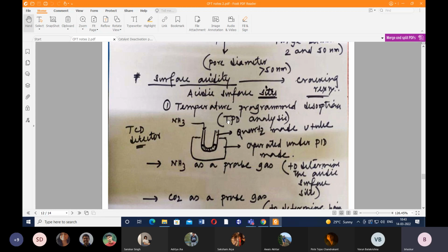This is treated as the active surface area or surface sites. In catalytic reactions, we talk about surface sites instead of surface area. By now you know what our active surface sites are and what our inactive surface sites are. On inactive surface sites, no catalytic reaction takes place. Now I need to calculate the acidic surface sites present in our catalyst material. Acidic surface sites help in various reactions: the cracking reaction, the hydrocracking reaction, and in the reforming reaction also, acidic surface sites play a major role.